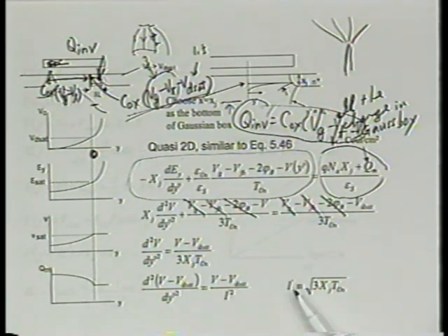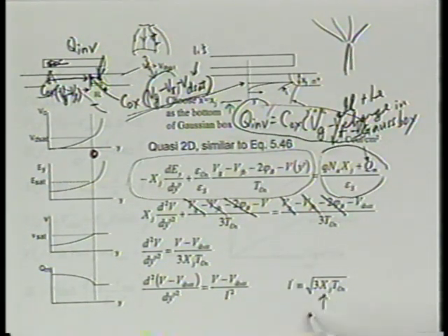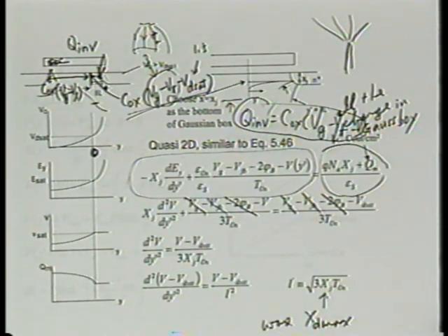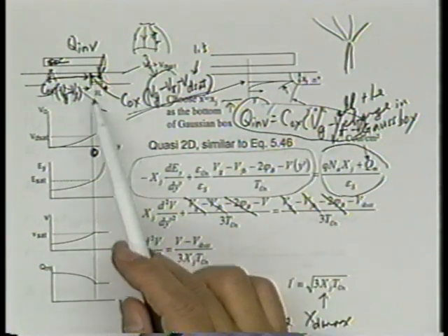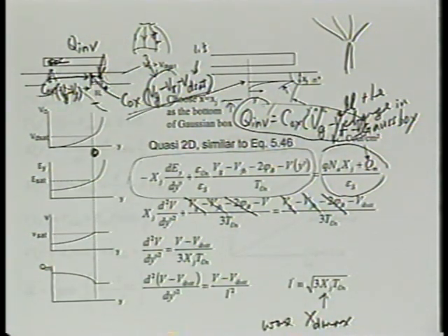I add a prime to differentiate from the L that we used in the drain-induced barrier lowering analysis, right? The difference is, in that case, we had xd max here. Remember? We had, what's xd max? Yes? Today we argued why xj would be a better approximation if we're only dealing with a region very close to the drain. Right? You following what I'm saying? Okay? So we call that L prime, just to differentiate these two characteristic lengths. But other than that, the equation is very similar.